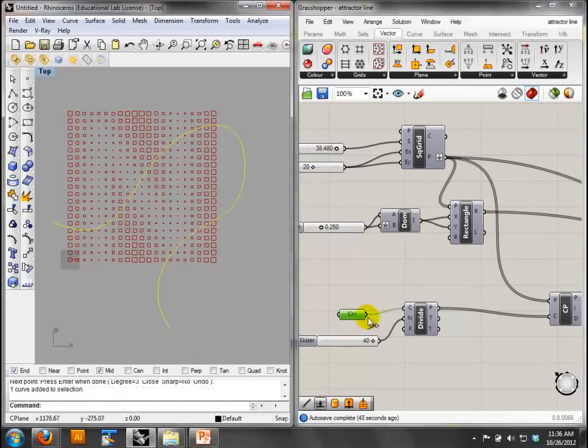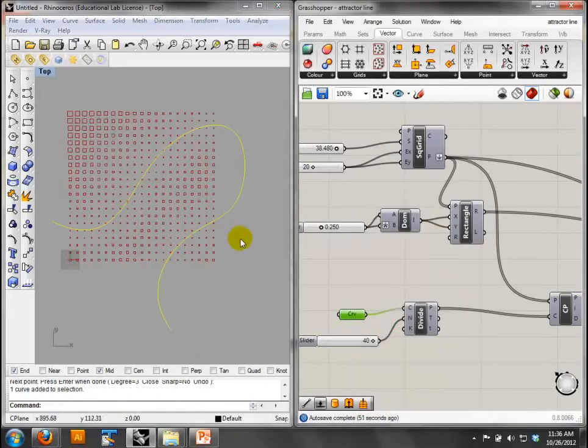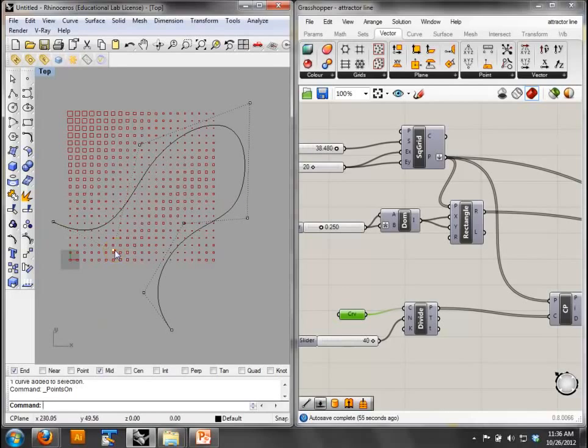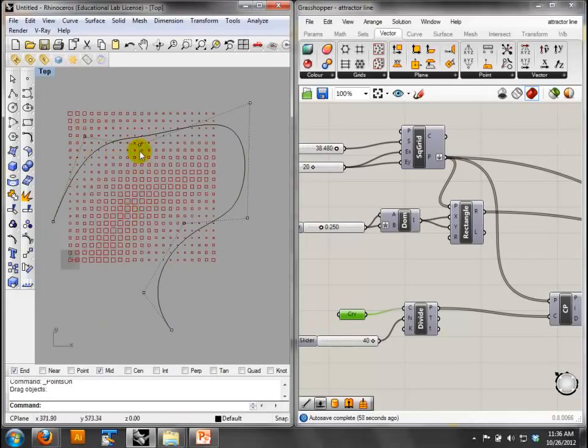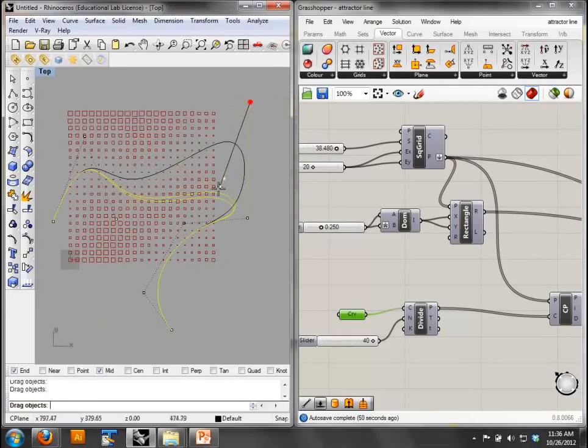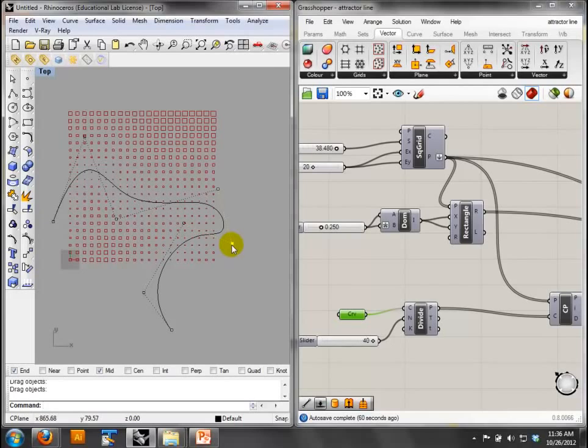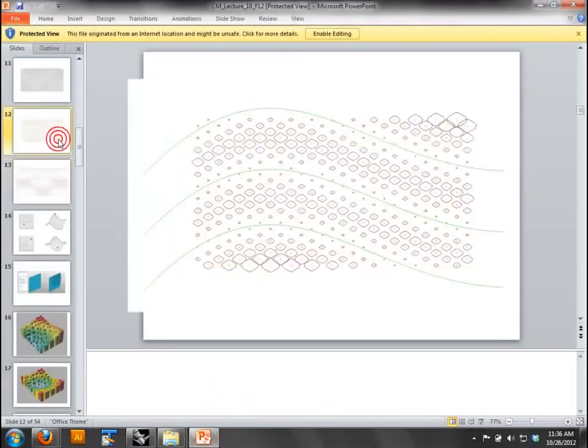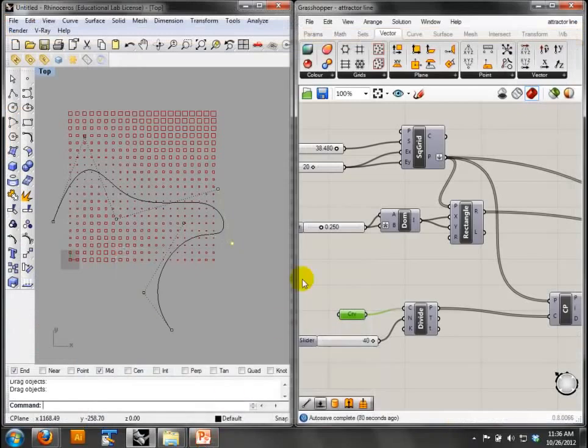So if I go in and I reference this curve, I can turn on the control points, and if I move it, it updates. And again, the curve could be parametric. You could do a curve, and you could do a move in order to create a series of those, right? And then plug those in, get the points from those. That's all it is, right? Get the points from them, and you can create those kinds of patterns. Send it off to the laser cutter, Mackenzie.